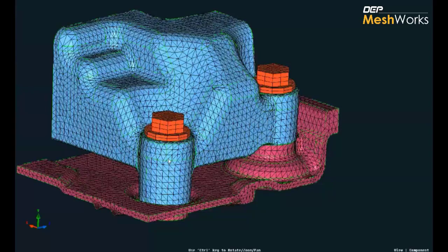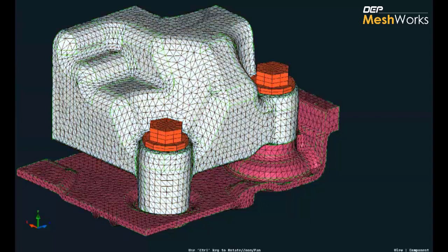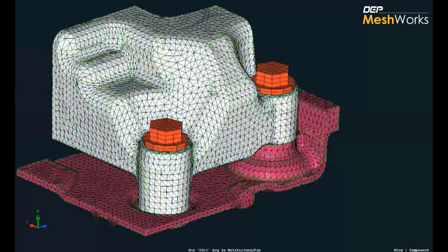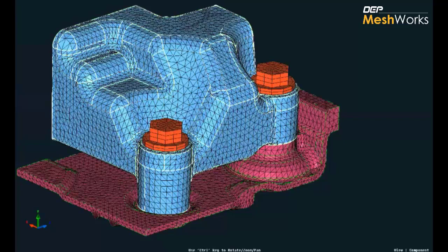So in this case, we are going to mesh the current part, the CAD part, with a different template since we want to do an NVH meshing. So I'm just going to select the current part. In this case, it's just a mesh, and then the new part, which is a CAD data. I set the new part type as CAD and apply a meshing condition.